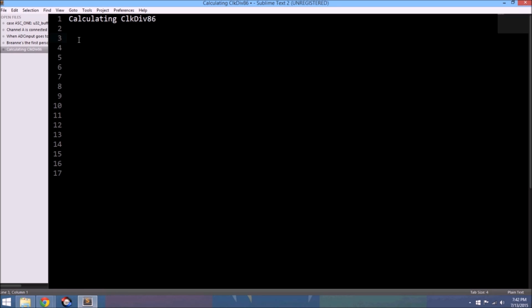So 9600 baud means that it takes 1 divided by 9600, equal to 0.104 milliseconds, to transmit a single bit. Well, there are 8 bits plus the start and stop bit. So you multiply that value by 10, which is just going to be 1.04 milliseconds. So the entire waveform of the UART message will take exactly 1.04 milliseconds.